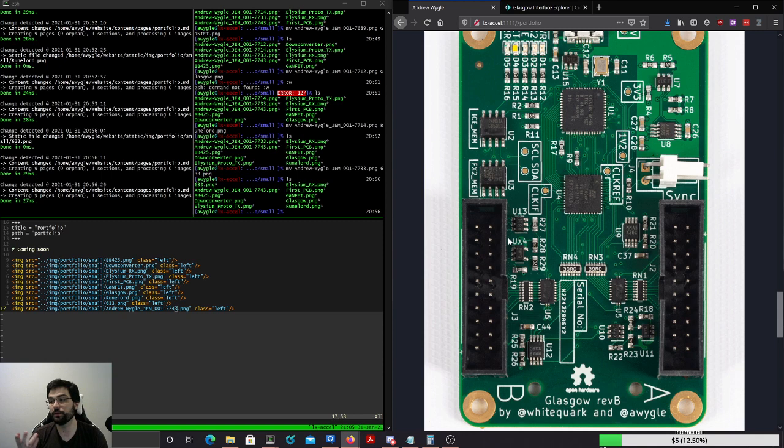So what we're talking about is Vapor Phase reflow. What I described is an oven, right? And you can have a couple different styles of ovens. I have a convection oven, there's IR, things like that. But an alternative is, instead of putting it in an oven, you do vapor phase reflow. There's this material called Galden that you can tune the boiling point of.